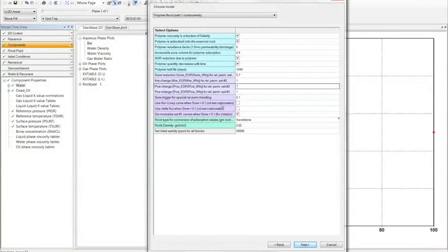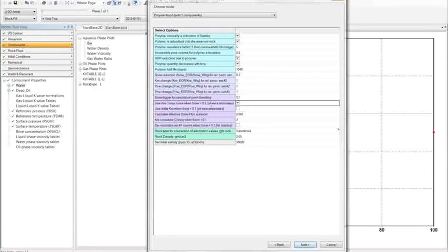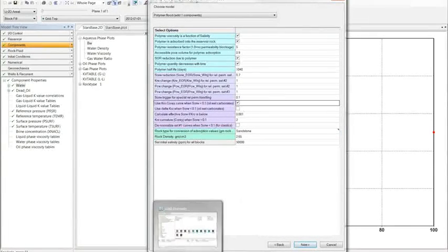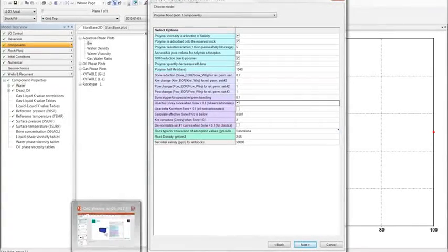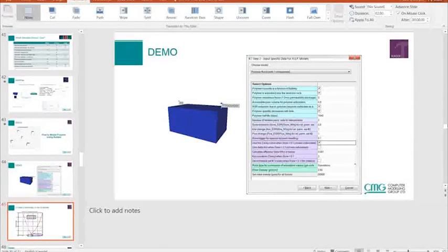Another case might be if your rel perm curves are normalized. This could be either clastics or carbonates. If you do have oil wet carbonate and this kind of a situation, probably it's best to use this first option here, to use this delta KRO, and there's a couple of inputs there. I'll just show you what the results could be from using that option.